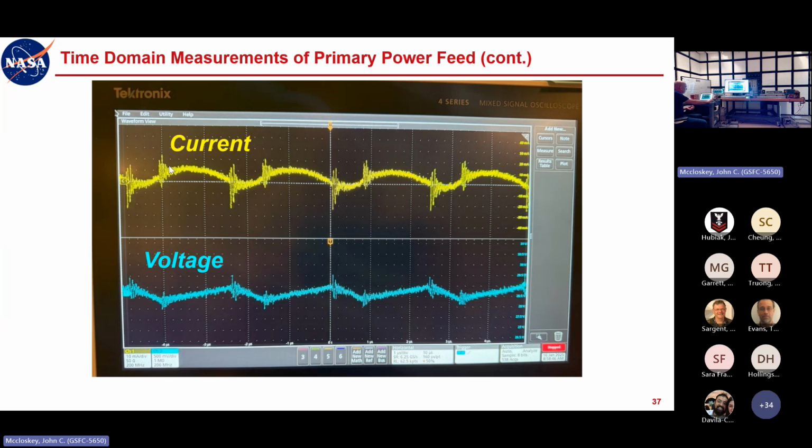The way it looks on the scope looks kind of similar, right? But here you see that the vertical scale is about 10 milliamps per division, and the one that I showed you was about 50 milliamps per division. So the peak to peak current is a good factor of 2 or 3 higher with the capacitor network in there. So bear that in mind. You can see that in the time domain already, and then we'll have a look in the frequency domain.